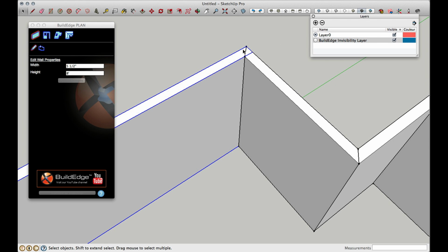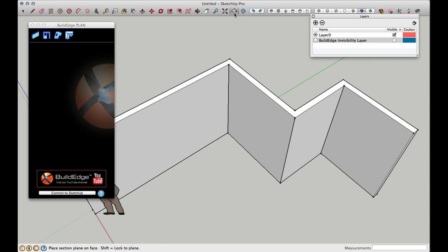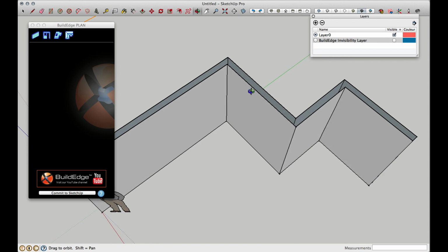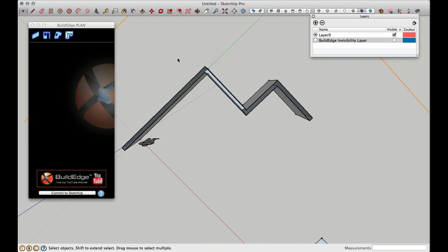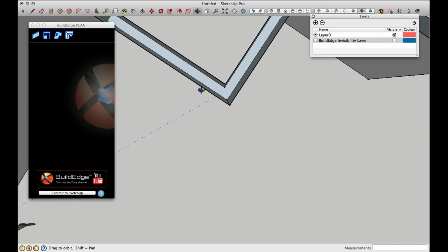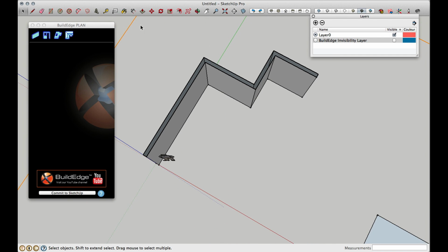So if I turn that on, I can see I actually have surfaces there. But we hide them so that when modeling, I get this nice, crisp looking model here. But more importantly, when I look at my section, I actually don't have anything top to bottom. This means if I'm creating layouts or creating drawings in layout, I can create my section view and have it look like just a continuous wall rather than having 45s at each of those angles. I'll delete my section right there.